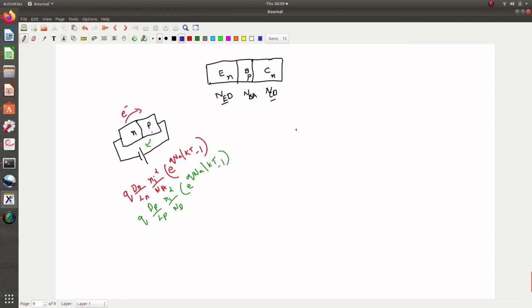In our earlier discussion, we had seen the emitter current is constituted by the current due to electrons from emitter to base and also holes from base to emitter. So this is the sum of these two currents, and we see Na is at the denominator here. Nd is at the denominator.